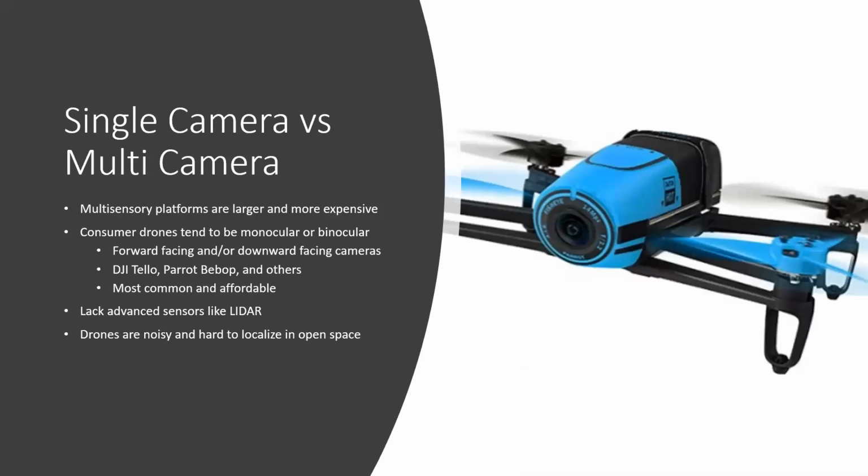But when we start to think about putting a vision or a mapping algorithm on a drone, there are very specific concerns we have to think about. Particularly on the cheaper platforms like the DJI Tello, the Parrot Bebop, which is featured here, and some of these other platforms that are around $1,000 or less, they don't tend to have a multi-sensory camera suite or LiDAR or any of these other things. You tend to get one forward-facing camera with like 16 or 14 megapixel resolution, and a pinhole downward camera with very poor resolution.